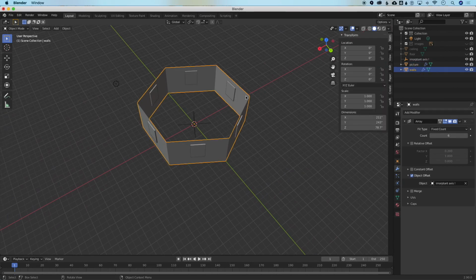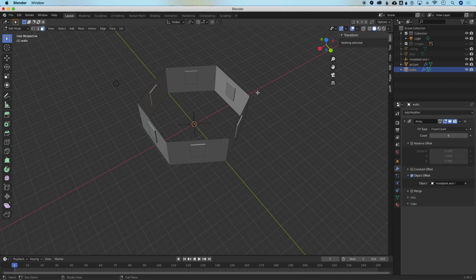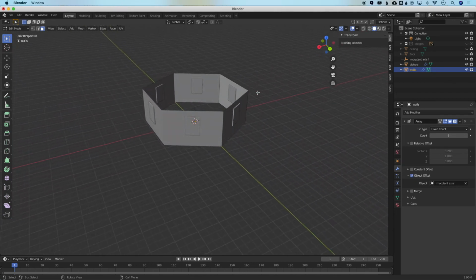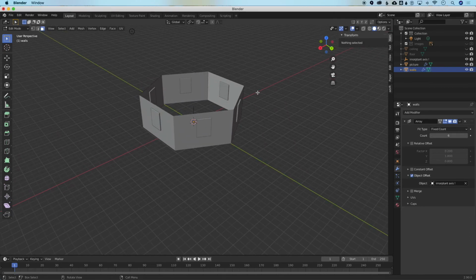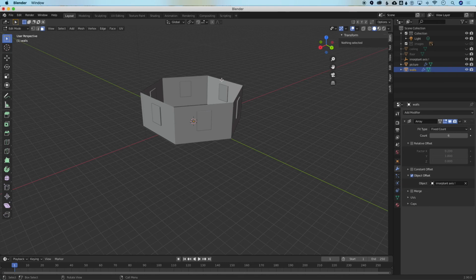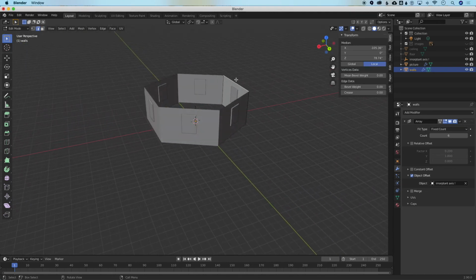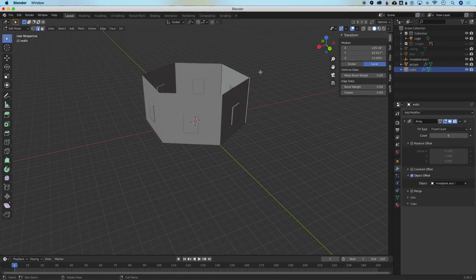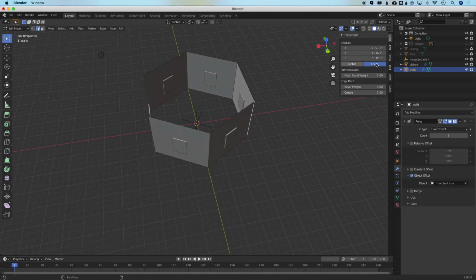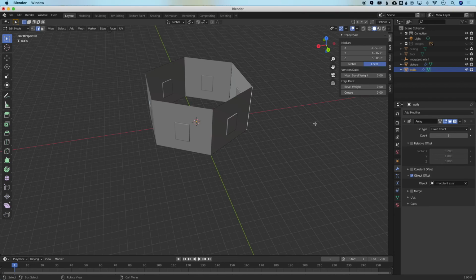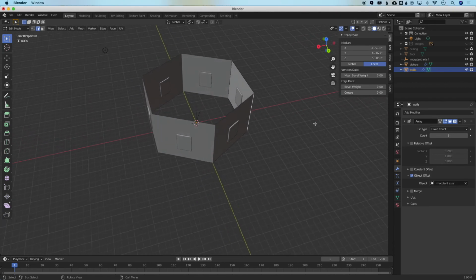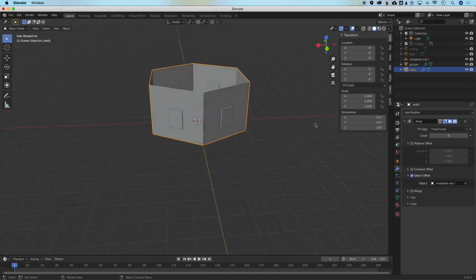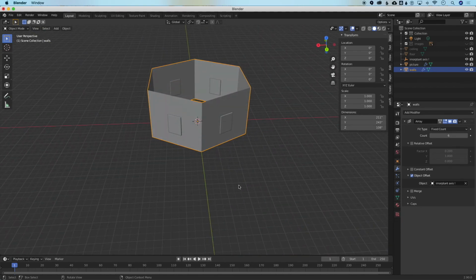Going back to object mode, I'll select the wall, I'll hit Tab again, and this time I'm looking at the space. I want to make the ceiling a little taller. So I'm going to press 2 to select an edge. I'm going to select the top edge of my scene. I will hit G and Z and just raise the walls up a little bit. There we go. And my ceiling is going to be low now, but we can deal with that later. So now I will look carefully at this. I will hit tab. So I am going to consider these walls done.